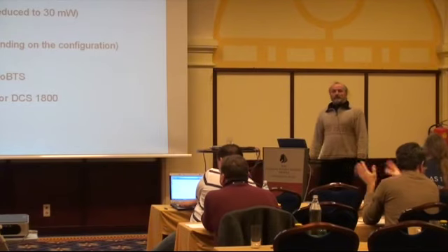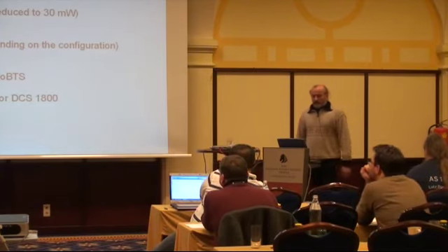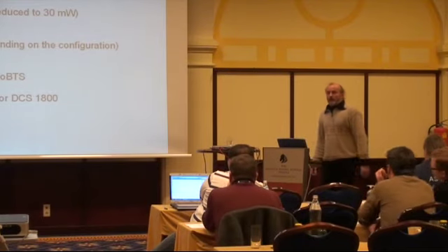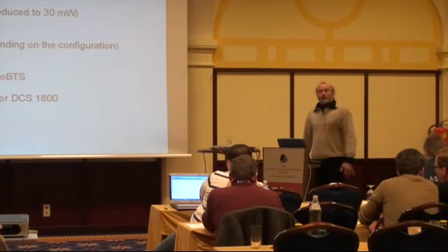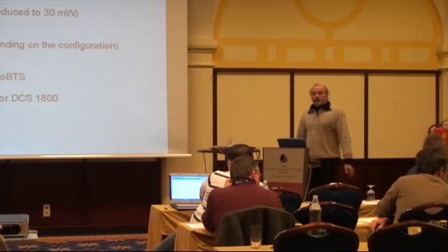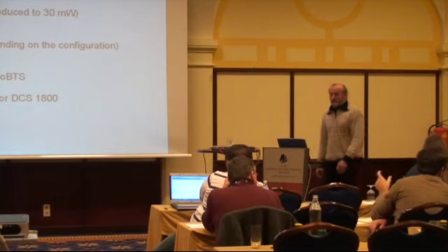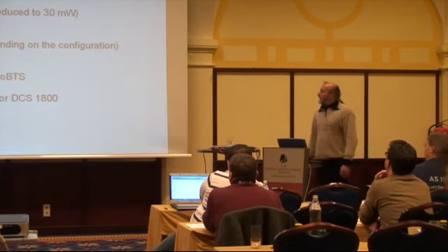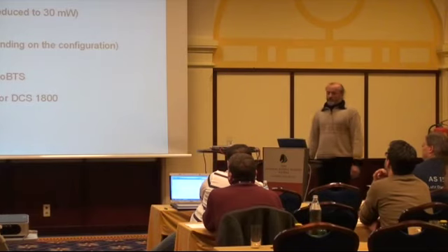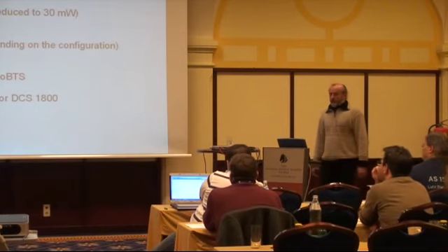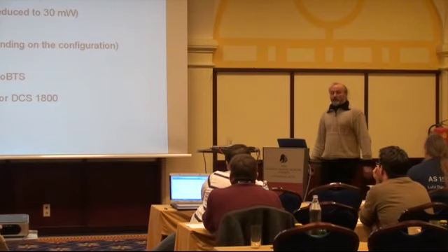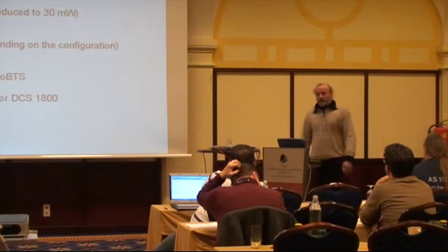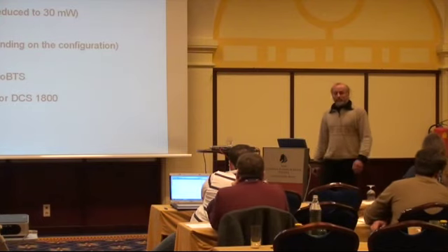As you can see from this rather low power, the Nano BTS is intended for indoor installations and to cover holes where the coverage of the standard net is not that good. It's also used on airplanes and on ships where you usually don't have any GSM at all. The Nano BTS is also available with GPRS and Edge, although this is not yet supported by OpenBSC. However, work is in progress, and you probably can expect GPRS support in OpenBSC soon.